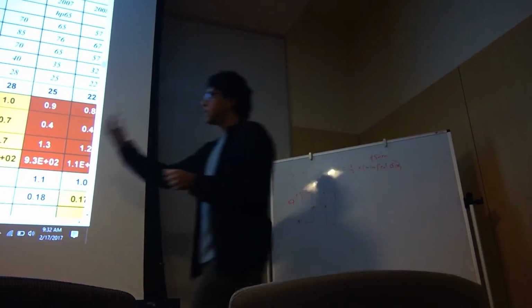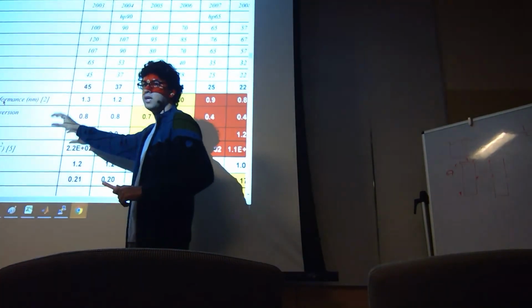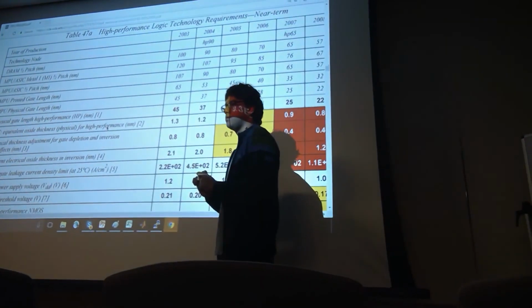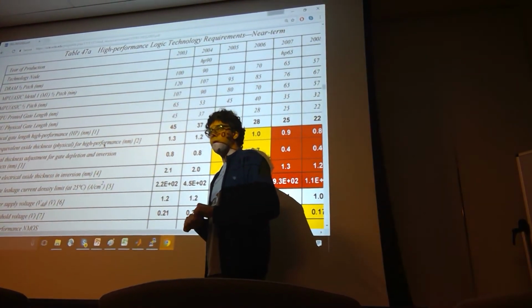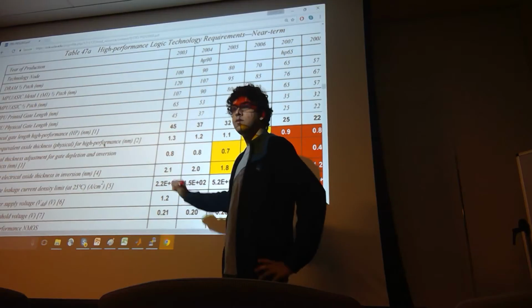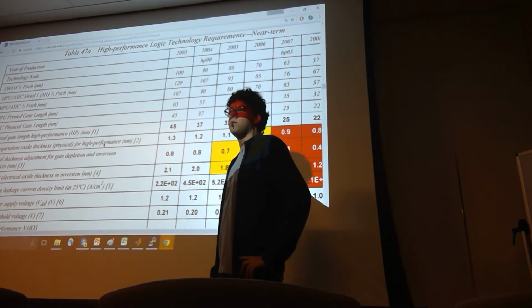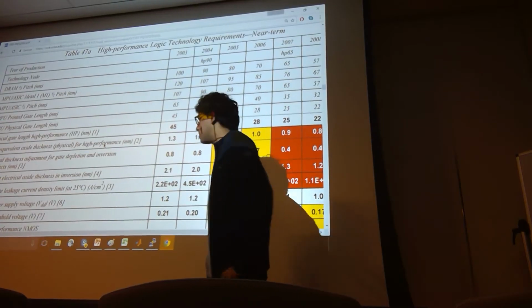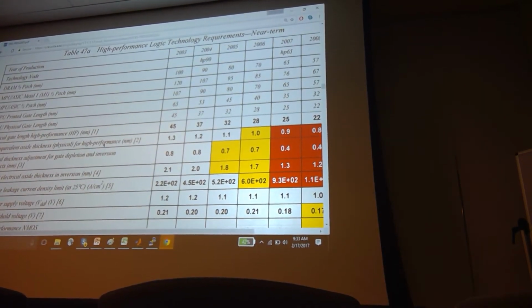So if you decide to use hafnium oxide, you need to multiply this by the ratio of dielectric constant in hafnium oxide to SiO2 to get your actual physical thickness in hafnium oxide. Is that 1.3? This is 1.3 nanometer, for SiO2. If you use hafnium oxide, just multiply by the dielectric ratio. So it will always be thicker with a higher dielectric material.